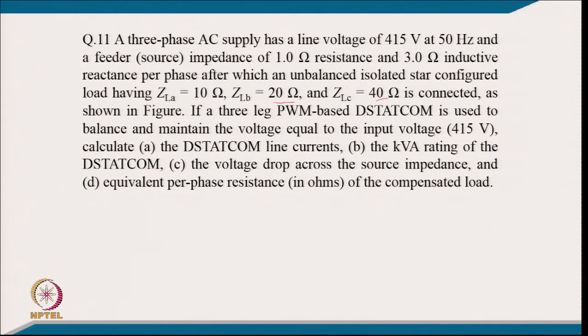And if a 3 leg voltage source based D-STATCOM is used to balance and to maintain the voltage equal to the input voltage, then calculate the STATCOM line current, kVA rating of the STATCOM, voltage drop across the source impedance and equivalent resistance of the compensated load.